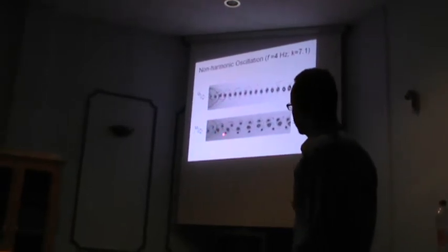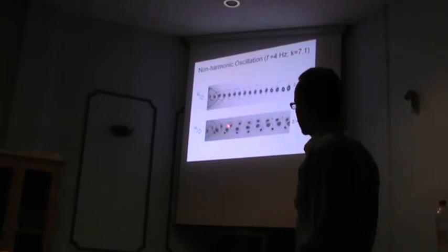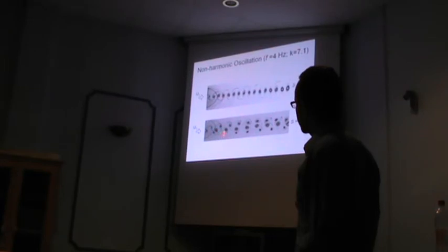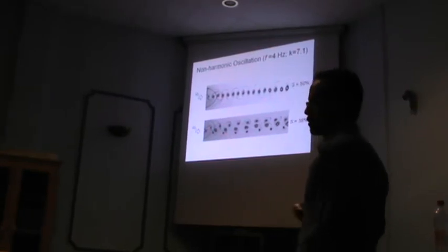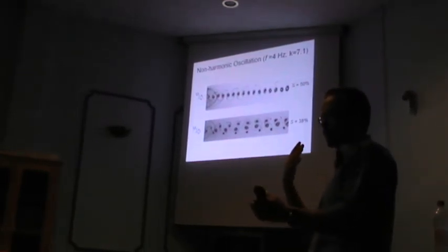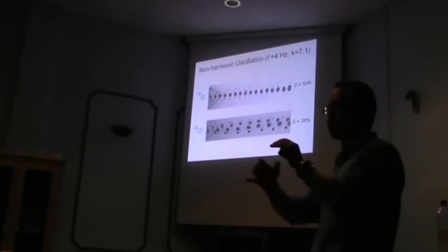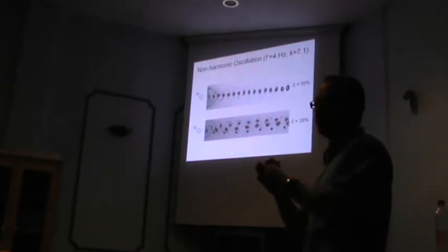You have two of these that have the same sign and one that has an opposite sign. And because of this configuration, see how the relative positioning of the vortex structure changes as they convect downstream. The mutually induced velocity between the vortex structures causes them to change orientation.